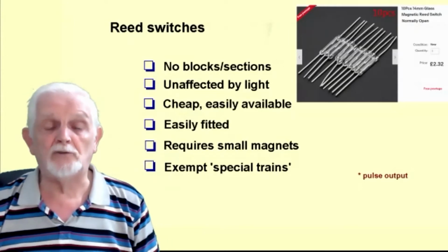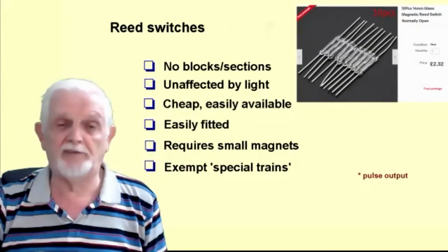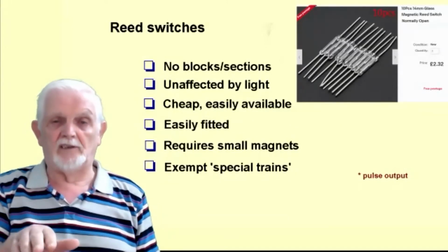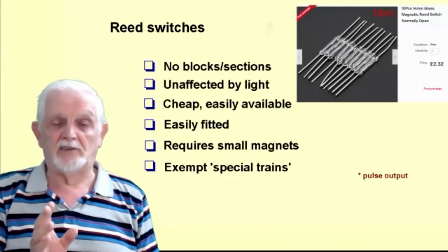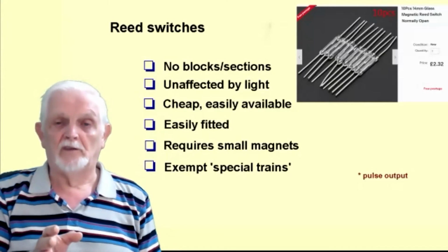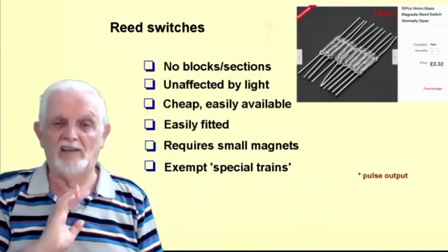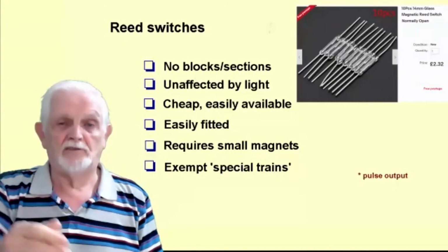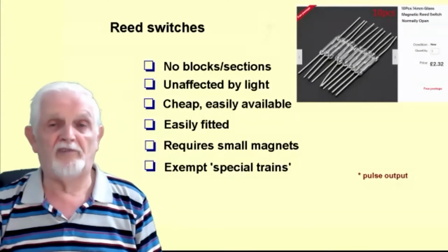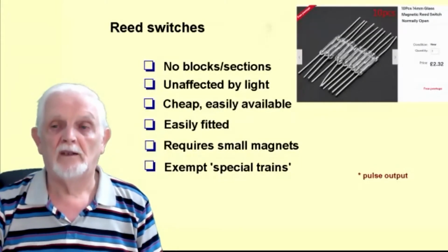It does allow you to do, as I said at the bottom there, you can exempt particular trains. If you fit a magnet, you can say, when I get to that detector, I have fitted those particular trains, goods trains, so they will be automatically routed that way. And every other train will carry on. So I'll operate points depending on how I fit magnets to different locos.